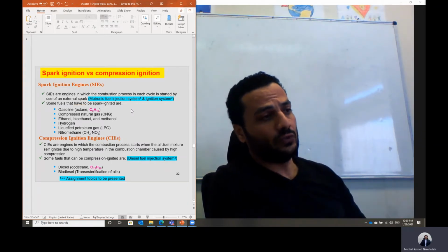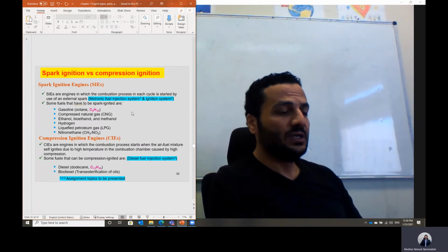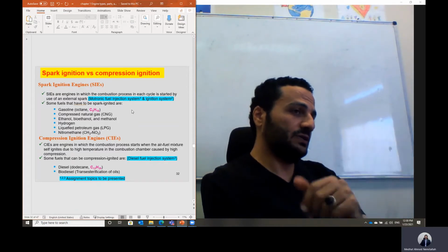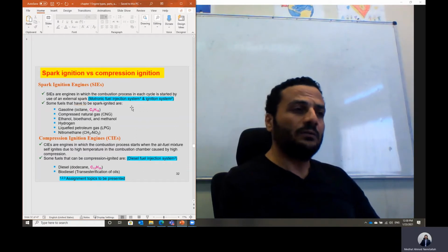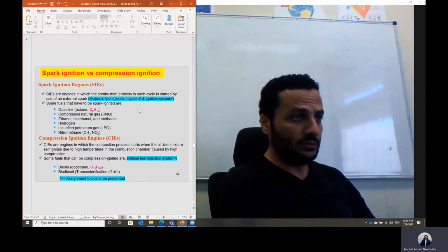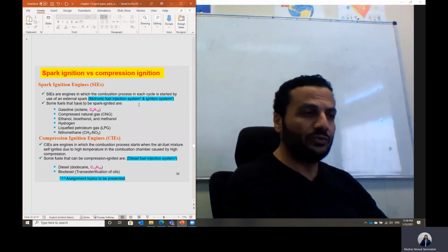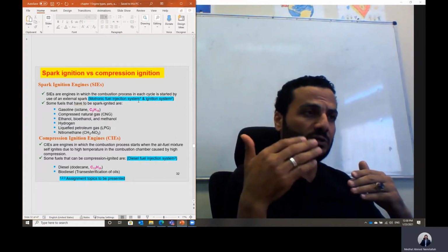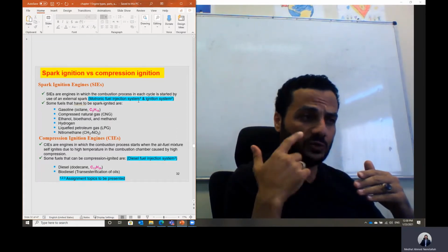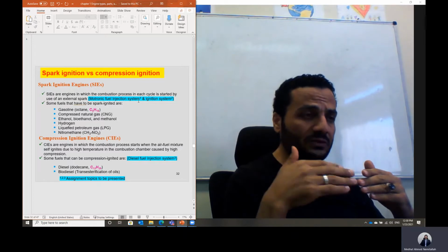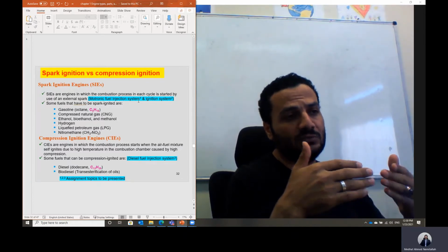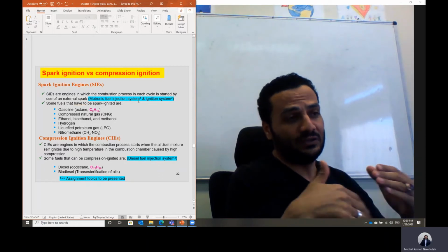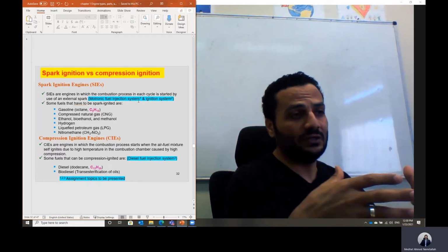And then we have moved to the Motronic injection system, in which injection of the fuel is electronic through the control from the electronic control unit, and also the ignition is electronic in case of Motronic. Even the Motronic system has different versions, ME Motronic, and at the end, in the year 2000, the MED Motronic was invented, which is gasoline injection, but it is direct injection. In this case, we call it gasoline direct injection.